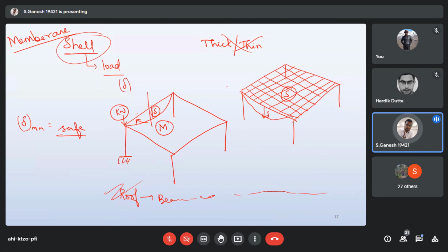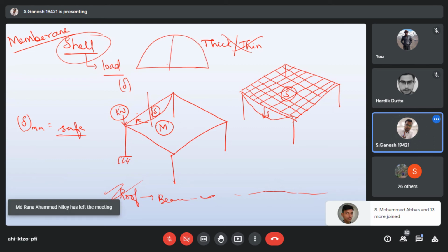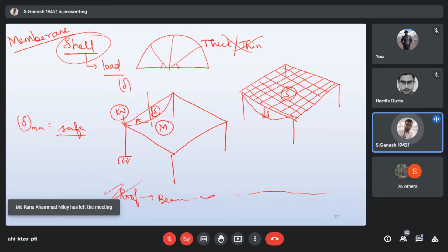inclined member. If you have some kind of inclined member or dome structures, especially dome structures like the domes in mosques, churches and temples. So where you see some kind of domes like this, we design these domes with shell elements. We divide this into lateral and longitudinal sections.